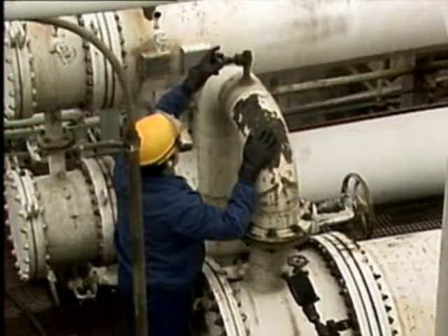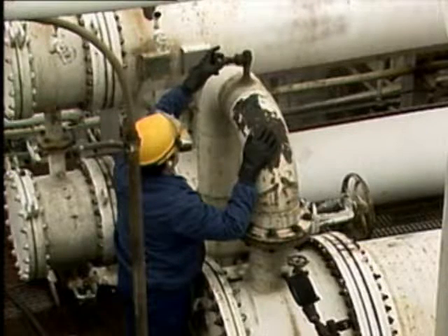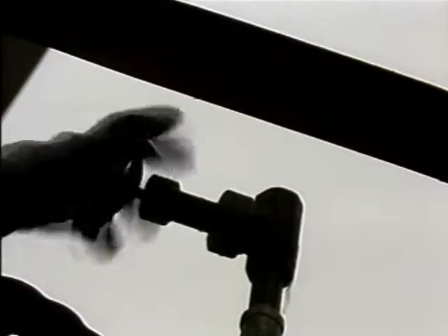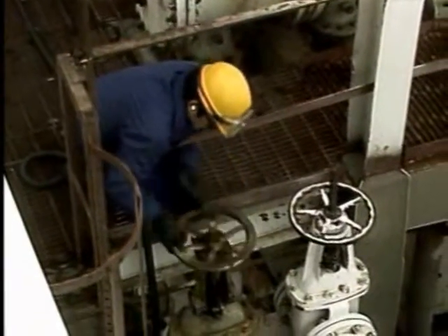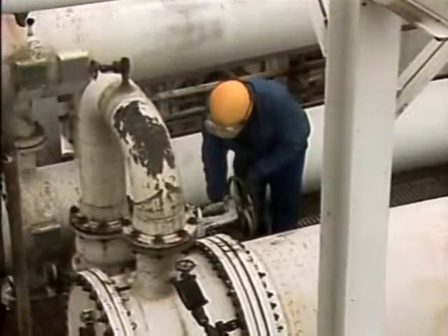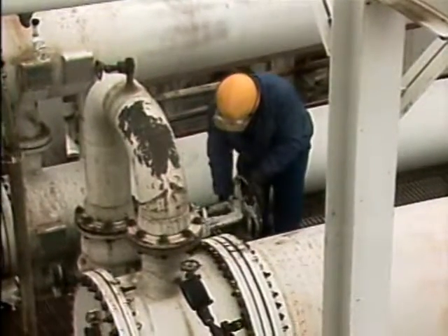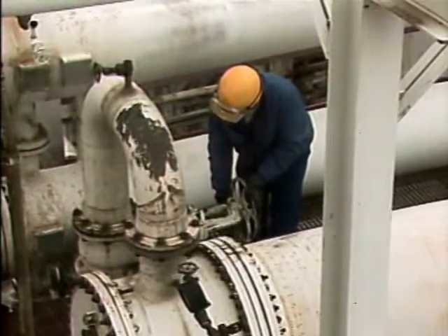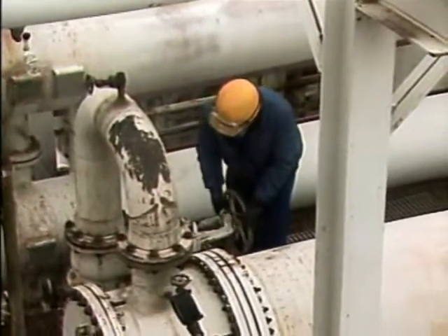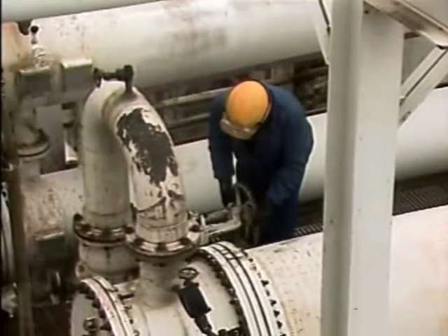The sound of escaping air means that cooling water is filling the tube side of the condenser. When the tube side is filled, a stream of water flows from the vent. Then the operator closes the tube side vent valve. With the vent valve shut, the operator fully opens the cooling water inlet valve. The cooling water flow is controlled by the outlet valve, so the operator partially opens the cooling water outlet valve to a predetermined position to establish flow through the condenser.